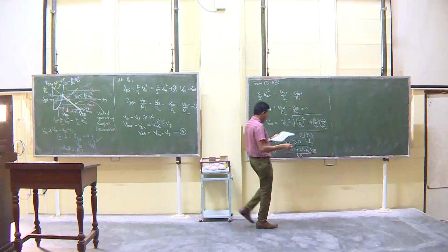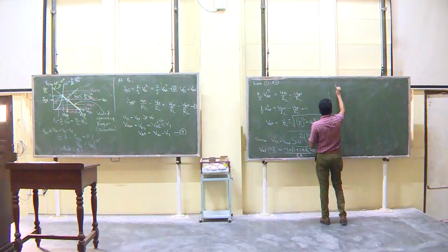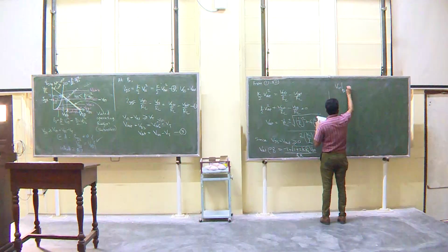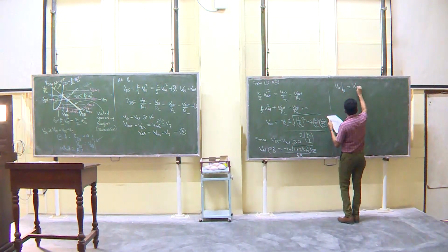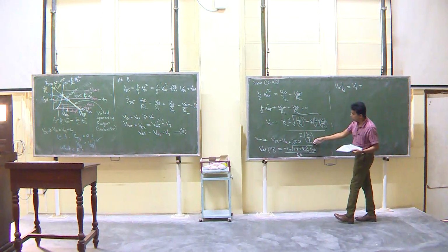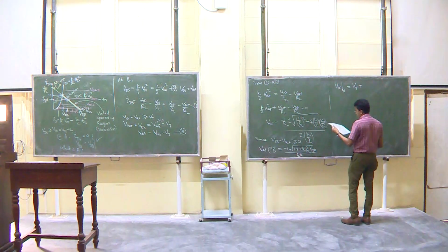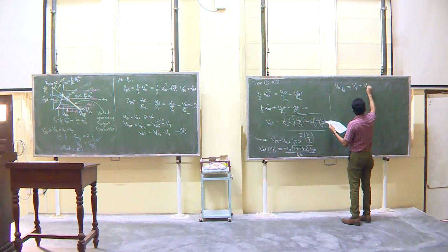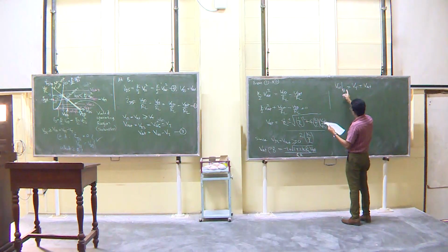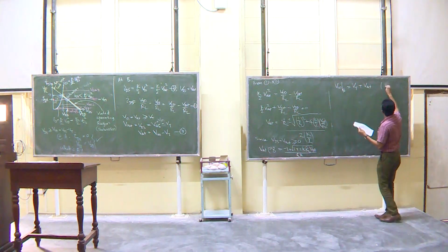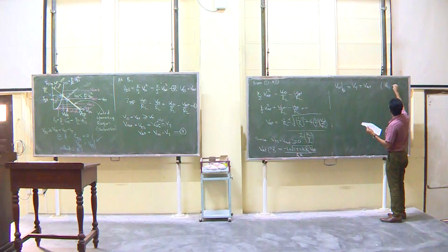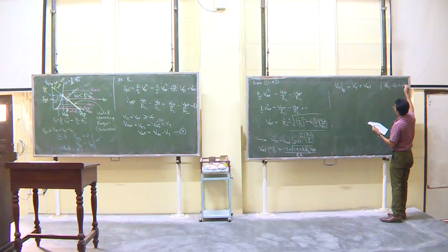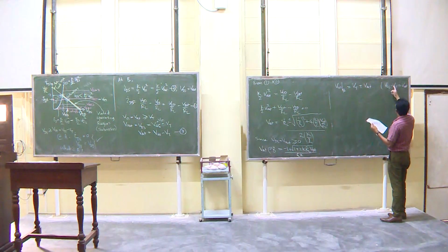So, at that point, V in at B is equal to Vt plus whatever that value, Vt plus V out. Vgs minus Vt is equal to V out or Vds. So, therefore, I have to add this to Vt to get Vgs.